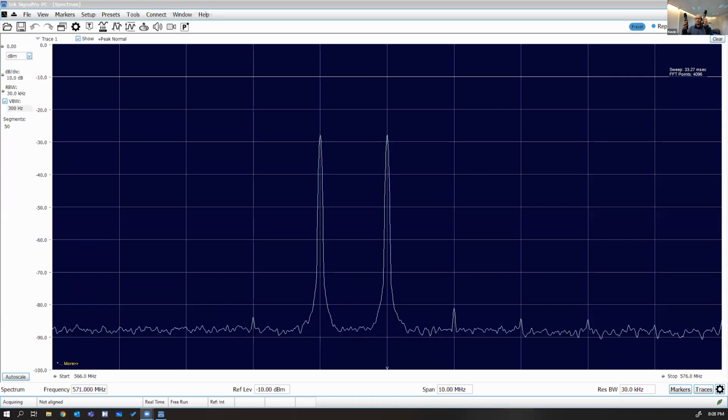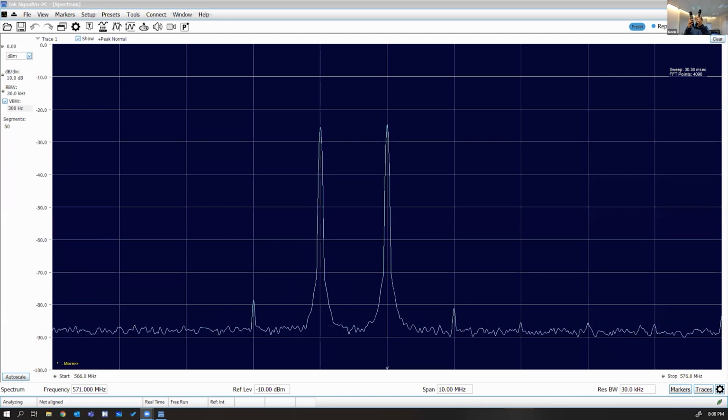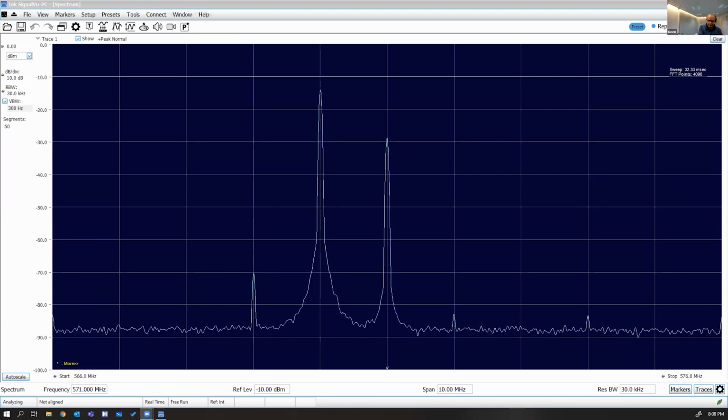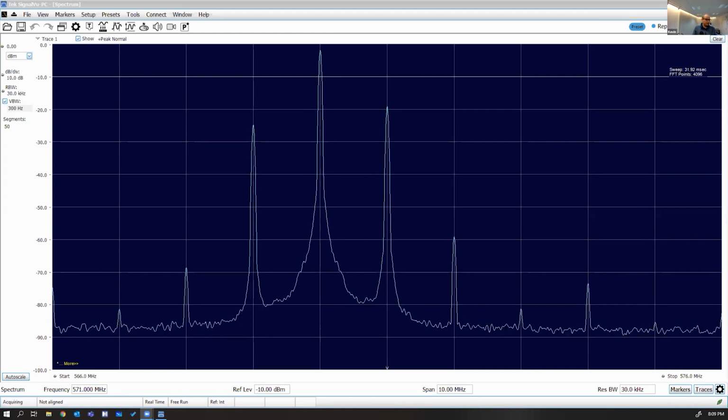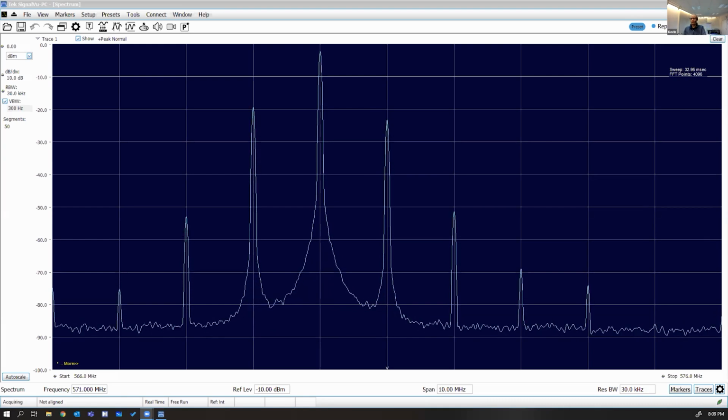What you can see now is once I get those transmitters closer together, there are more spikes coming up in the spectrum. These are the intermodulation products. They're basically virtual carriers. You can operate another system on those carriers, but as Greg mentioned, there is a possibility of distortion, there's a possibility of higher noise, and it greatly reduces the range because you have interference below your carrier. Let's switch on the third. This is the third now, and let's switch on the fourth, and then I'm going to put them all together in a big pile, and you see what happens.